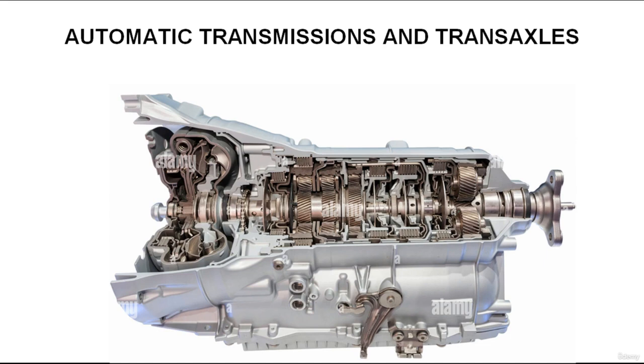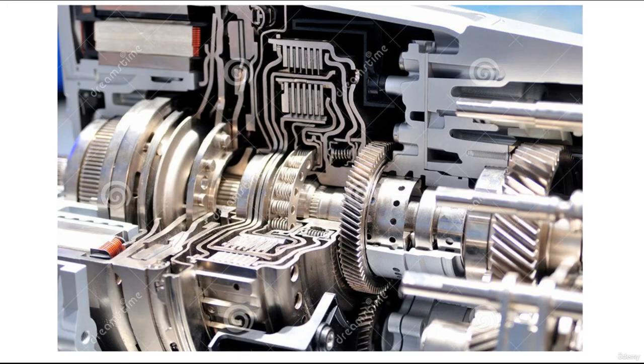Little effort is needed on the part of the driver because both upshifts and downshifts occur automatically. A driver-operated clutch is not needed to change gears, and the vehicle can be brought to a stop without shifting to neutral. The driver can also manually select a lower forward gear, reverse, neutral, or park. Depending on the forward range selected, the transmission can provide engine braking during deceleration.